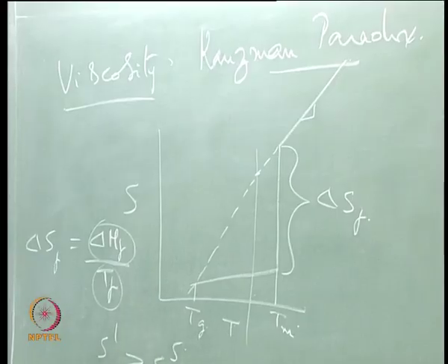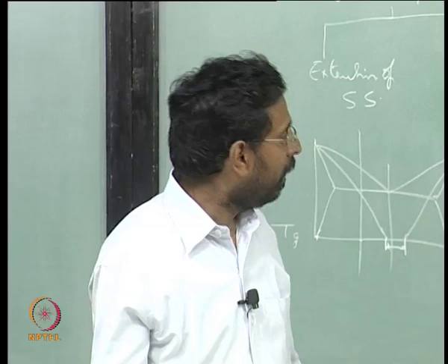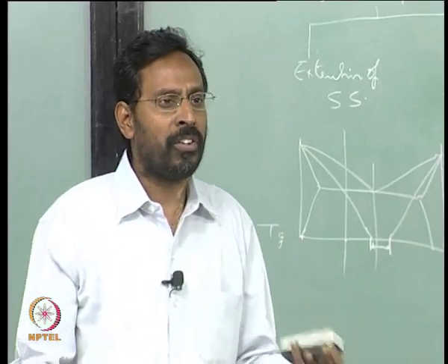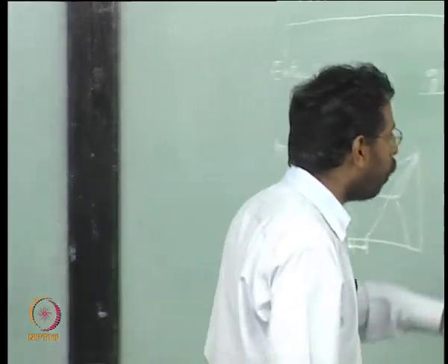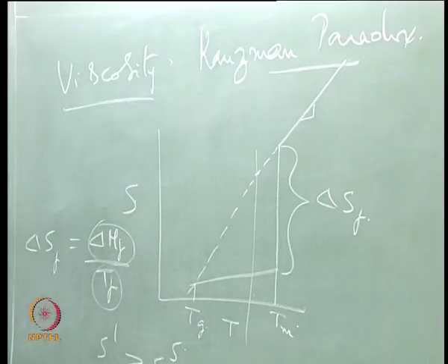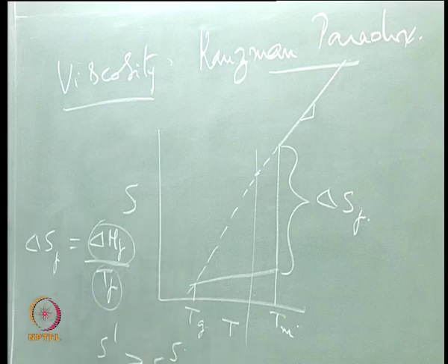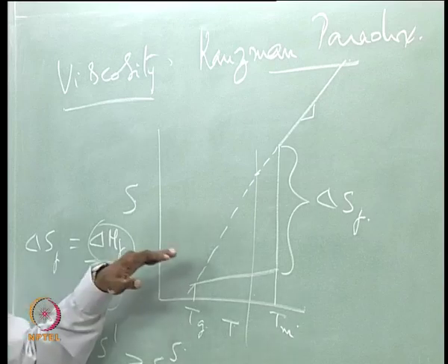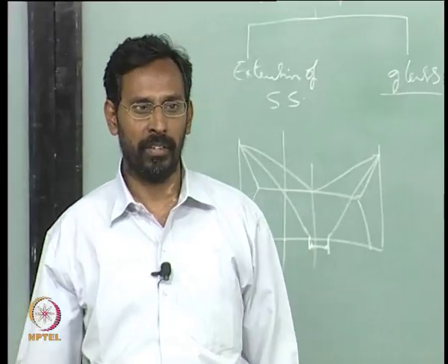temperature. The thermodynamic definition of a glass transition is where the liquid freezes into some structure, some solid structure, in order to just avoid becoming a crystal, of having a situation of lower entropy than that of the solid. So, just to avoid this particular paradoxical situation, the liquid becomes a glass, and that particular temperature is what we call the glass transition temperature.